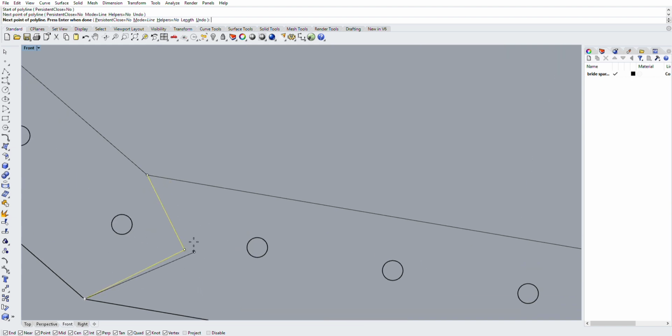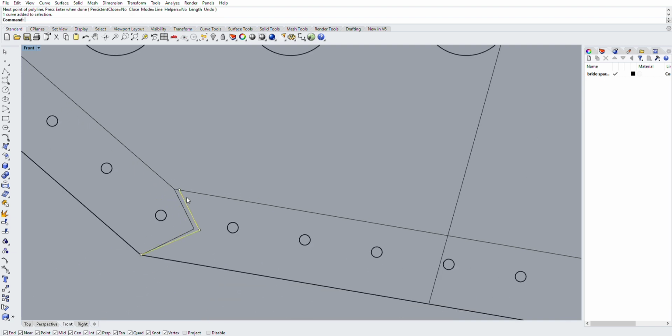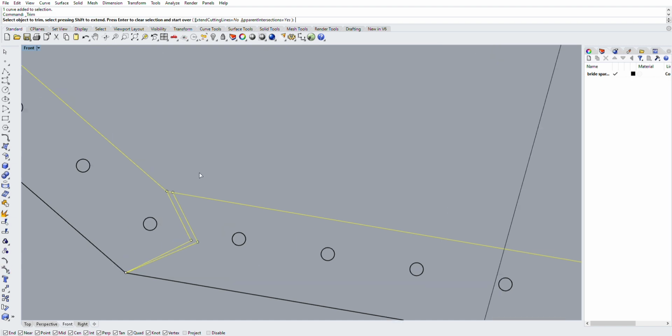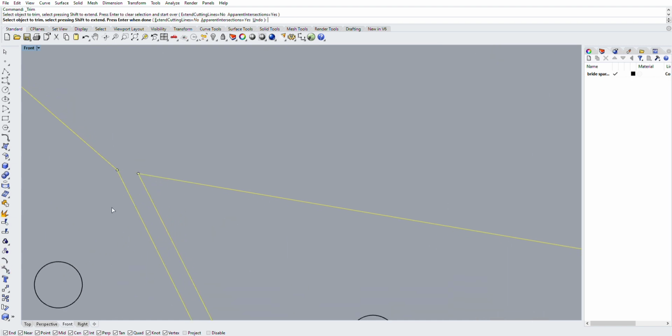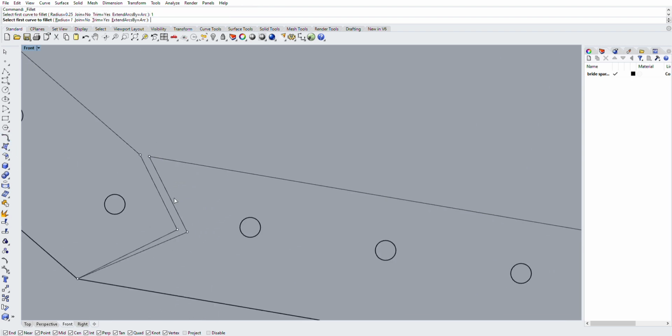But I do need my flanges to not touch. It could literally be 1/10,000th of an inch. It doesn't really matter to the software, but for the commands that I'm using, I can't have them touching. So I go in and use my trim tool, remove the lines in the middle, and the points look kind of funny. So I'm going to use the fillet tool and radius these.